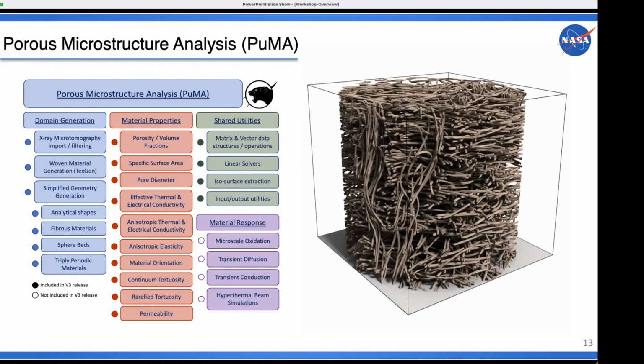So if you want to simulate heat transfer here properly, you need to take that into consideration. And part of that, you have to then know how each voxel in your three-dimensional domain is oriented. So we have techniques to try to estimate from micro CT data what the orientation of your material is, assuming it's woven or assuming it's some kind of fibrous material like this.